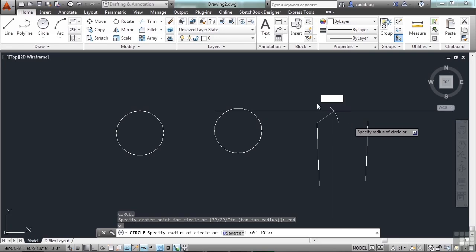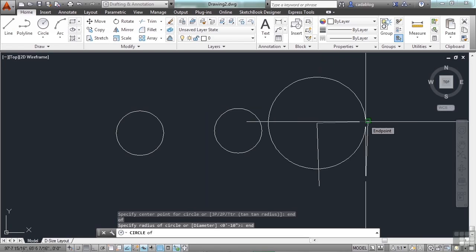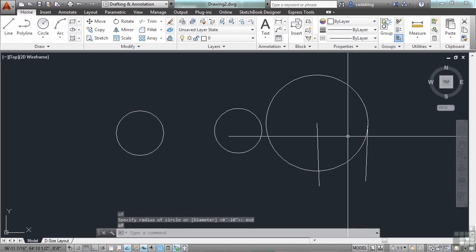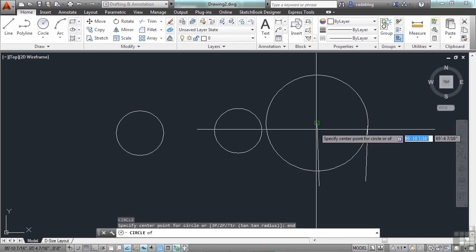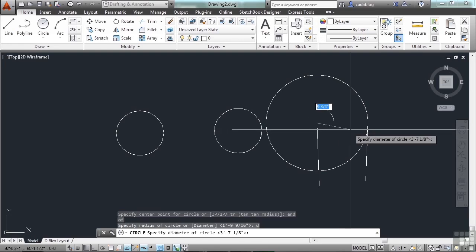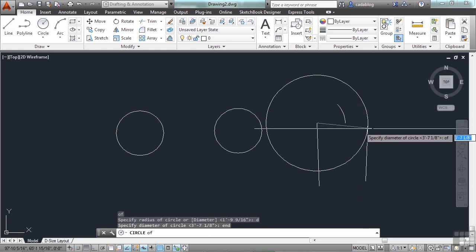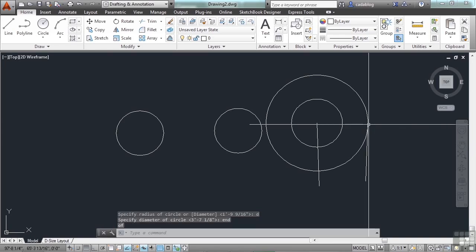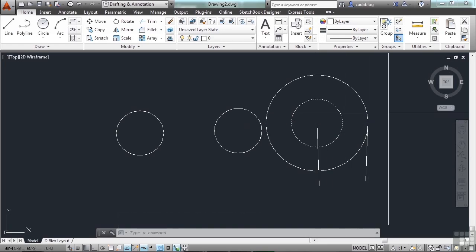I'm drawing with the radius now. So I will type in end for my endpoint and draw there. That's my circle. Let's start again, the circle command. Type END for endpoint. We're snapping to the endpoint of this line. But now hit D for diameter. Press enter. As I stretch, I'll type in end again and go to the endpoint of that line. And there you go. I just found the middle point between these 2 points, drawing a circle.